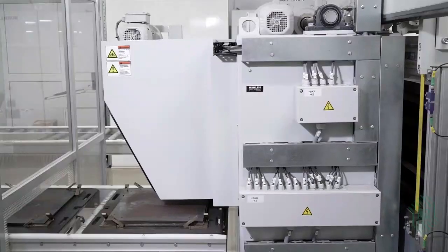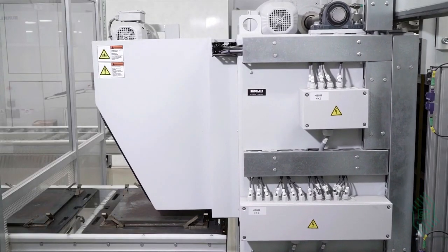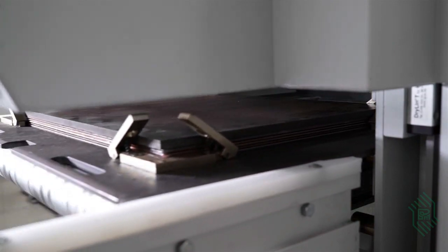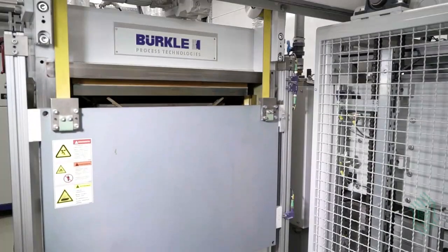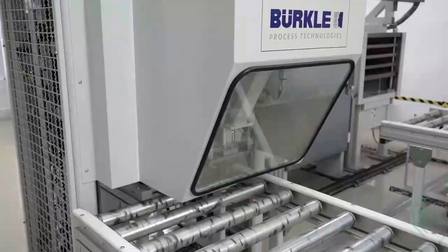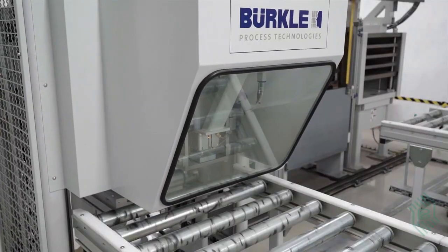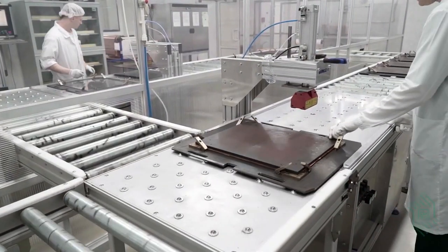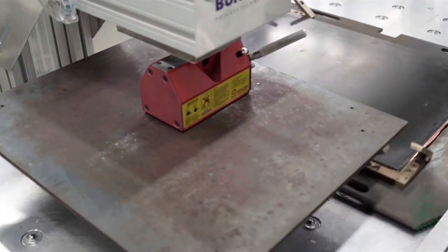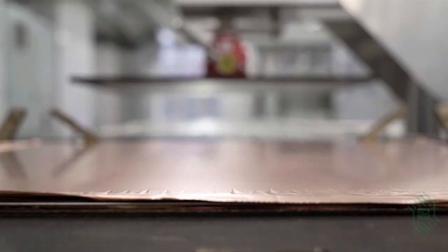The press forms are gathered together and loaded into a hot vacuum lamination press. During lamination, the panels are bonded into a single structure. After hot bonding, the panels are moved to a cold press for controlled cooling. Then, the press forms are taken apart and the laminated panels are transferred onto the registration holes drilling stage.